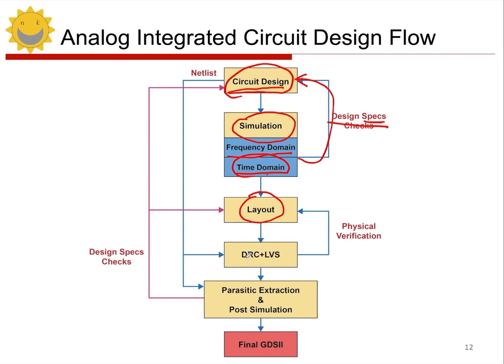Initial design may have issues, i.e., insufficient margins. Even with optimized layout, it may not meet specs if margins are insufficient. In this case, modify circuit design. If post-simulation fails, modify layout or design. Usually failure is due to poor layout. If post-simulation passes and meets design parameters, generate final GDSII for tapeout. This is analog IC design process.